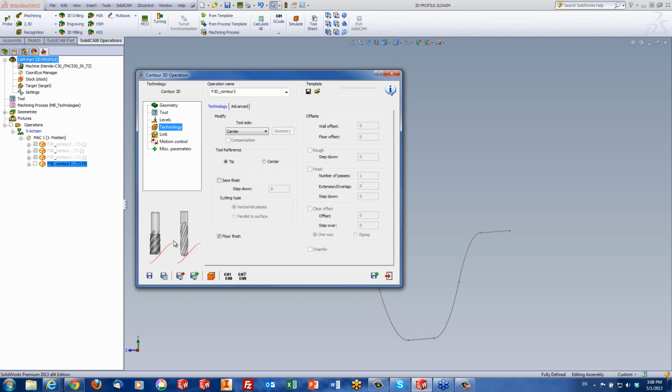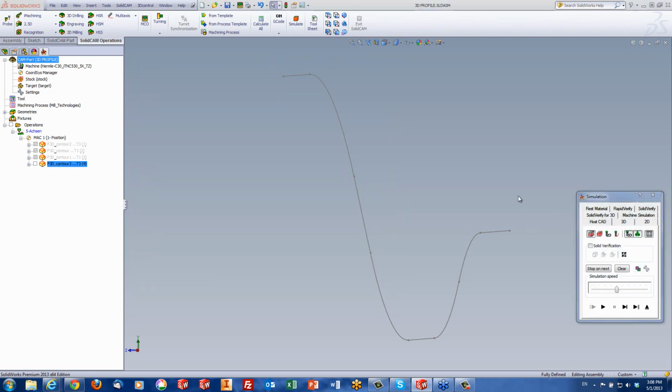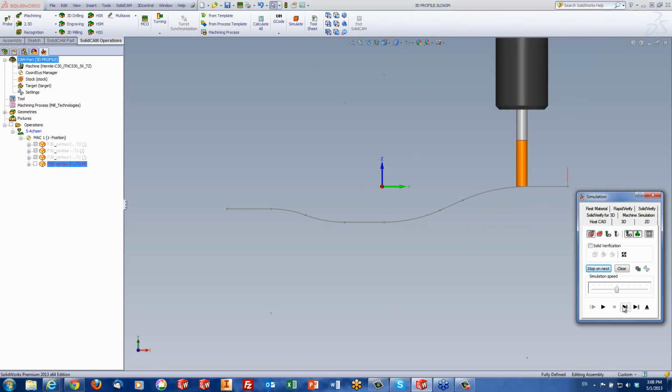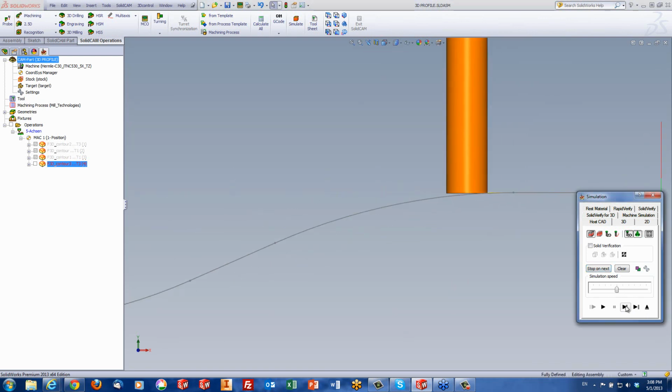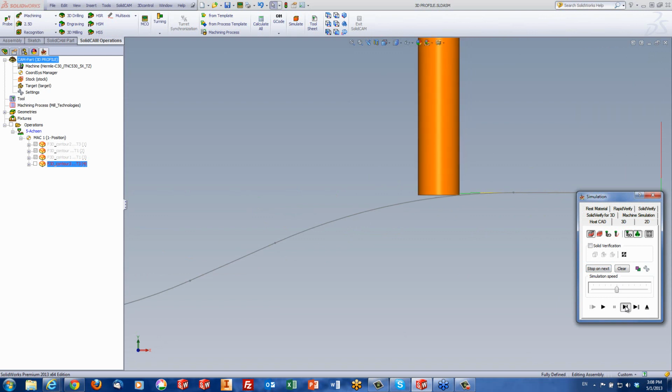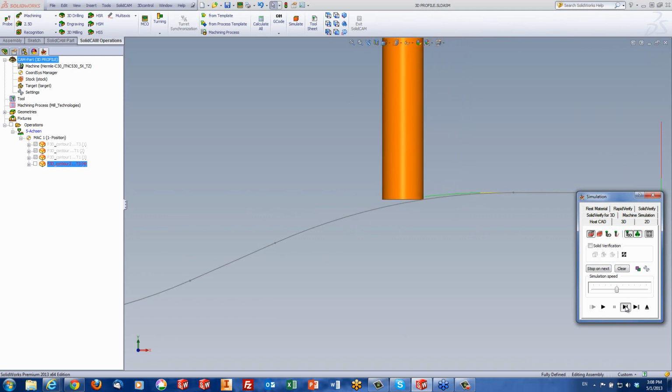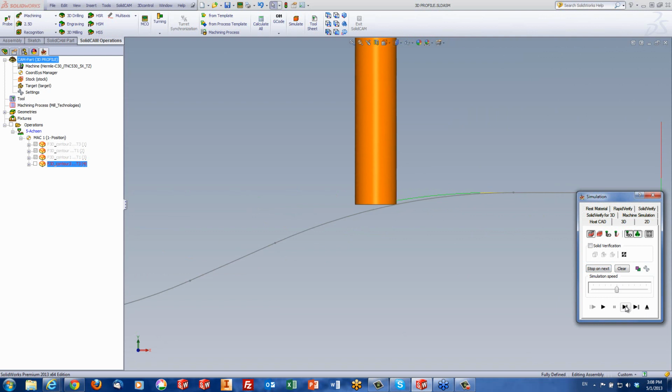But if I'm using a regular end mill, you'll see that the edge will actually be following that particular line. Let me actually run it right now with the regular end mill that I just showed you. And this time I'll show the side view of it. You'll see that the tool will go down. And note what happens, and I'll try to zoom into this area over here. What actually happens is the tip is always what is touching the geometry itself.